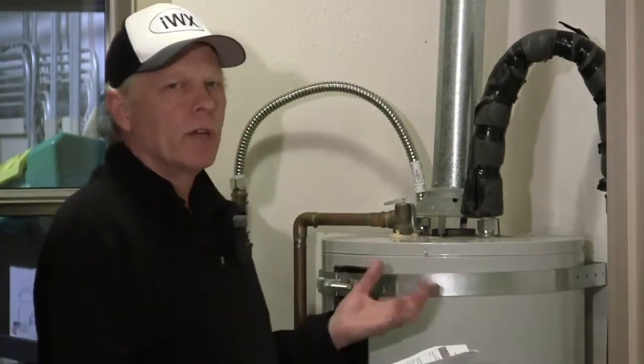So earlier we determined that the greatest depressurization in this combustion appliance zone was caused by excessive exhaust, and that is one of the three choices of the test results. And if this did spill, there's an action required based upon excessive exhaust being the problem. You need to become familiar with this entire sheet, but table D1A is very important to know to complete the test and complete it accurately.